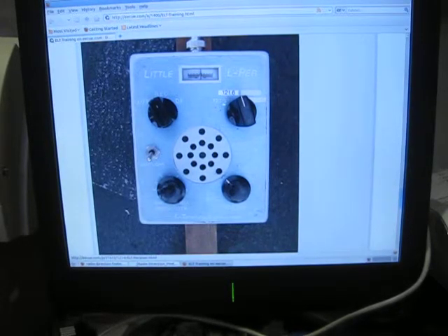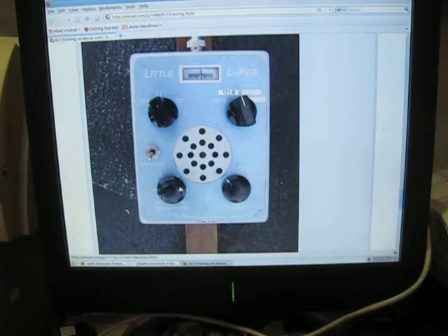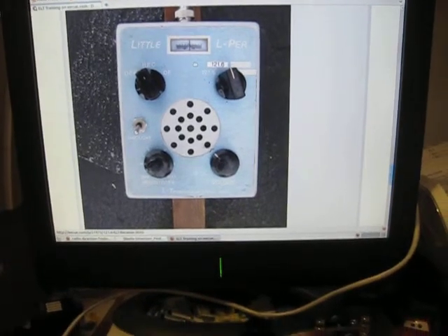There's nothing really, and you have a sensitivity adjust. You can do this with a resistor decade box as well, in line with the handheld. Or you can switch off frequency, which is another little trick I'll show you in the next video. So here you go, off, receive, DF. So when you're in receive mode, it shoots up that voltage and turns on that diode and turns it into a Yagi. When you're in DF mode, it has that oscillator in there, and if there's a difference in impedance on those two diodes, it'll have a null or it'll have a tone, and that tone's determined by your oscillator